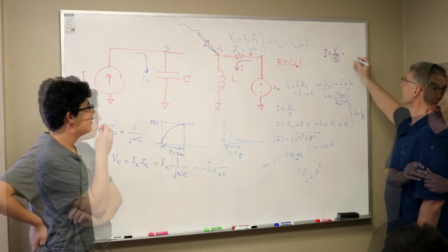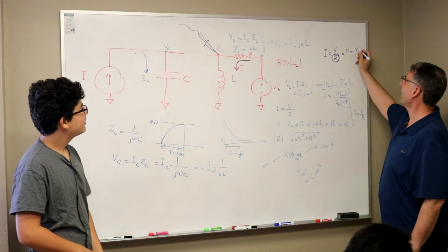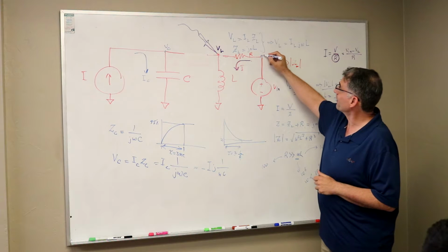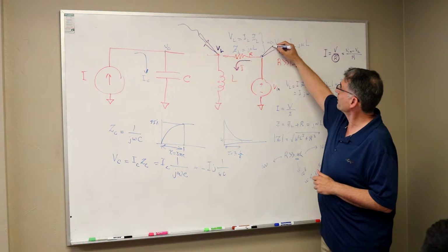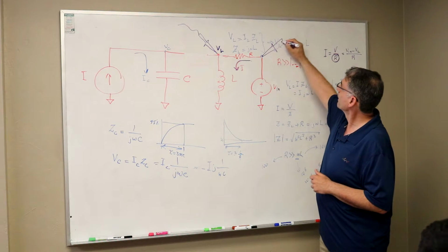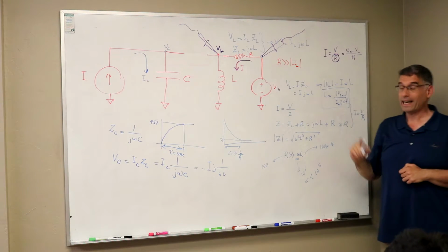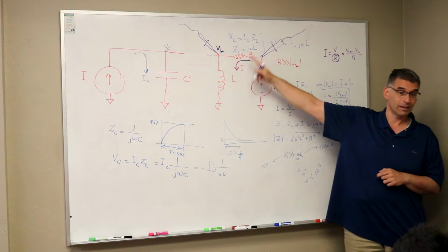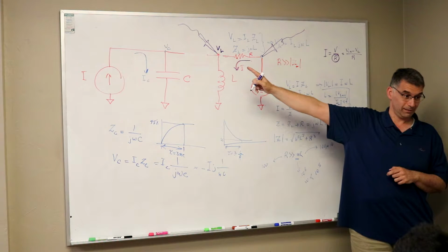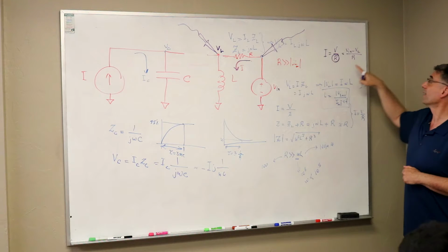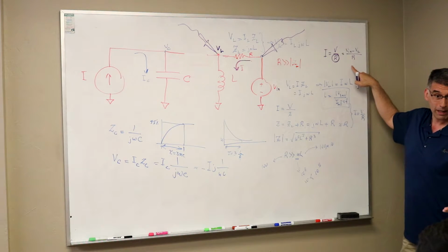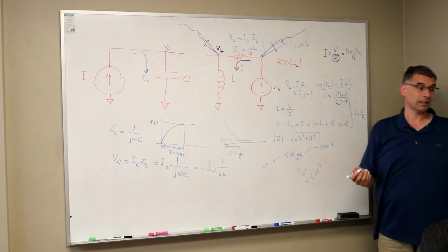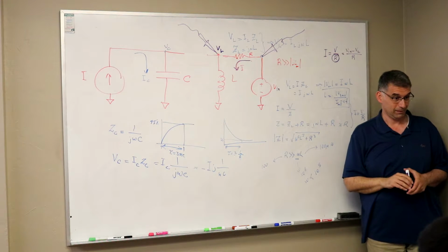It's V in minus VL, over R. So that's why I need another probe here. Now I can do the math function that says V in minus V out to measure that, and then in my spreadsheet, I know what R is, I do the division and I get the current. Okay?